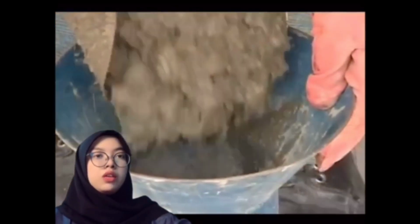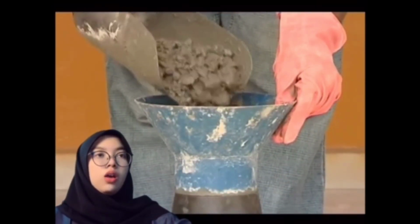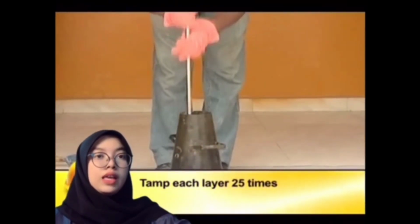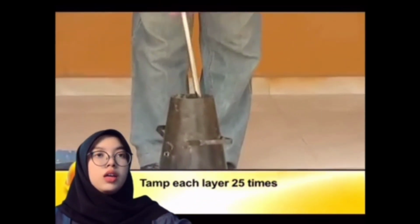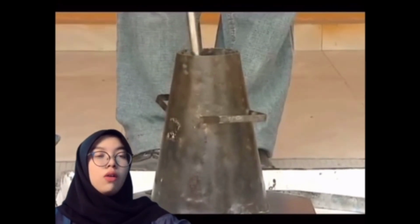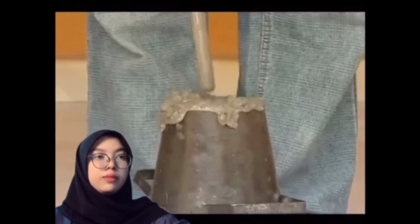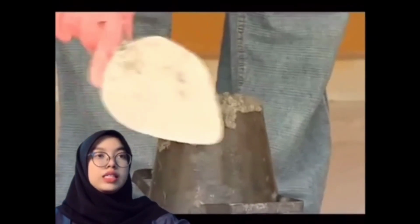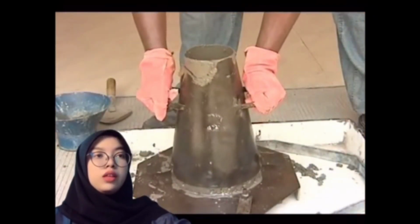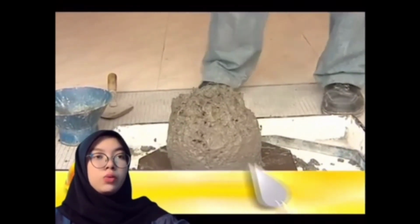The mold is placed on a smooth, horizontal, rigid, and non-absorbent surface. It is then filled in layers, with the thickness of each layer being approximately 1/4 of the height of the mold. Each layer should be tamped 25 times evenly. Use the rounded end of the tamping rod such that strokes are uniformly distributed over the cross-section. After the top layer is tamped, the concrete is leveled with a trowel so that the mold is filled exactly to the top. The mold is then removed by raising it gradually.